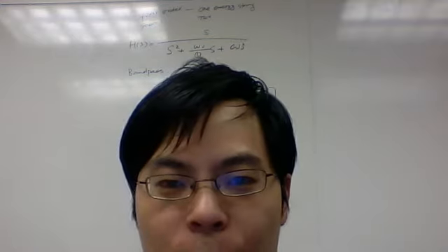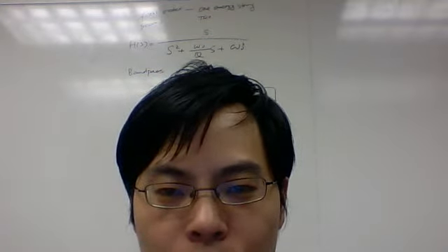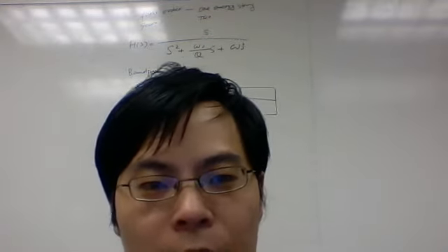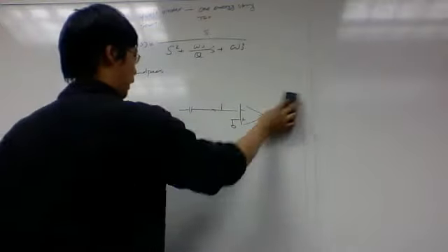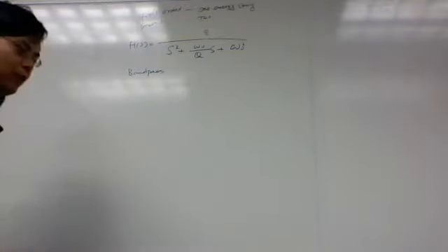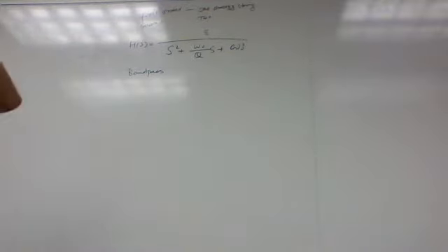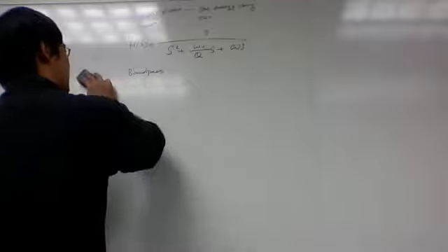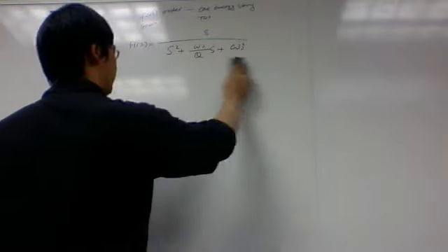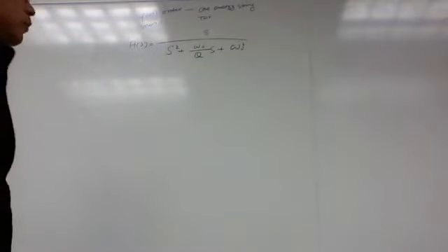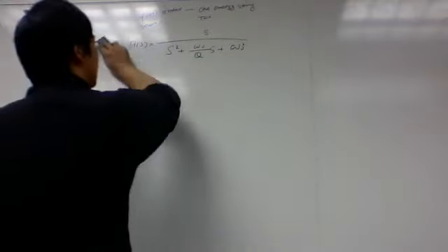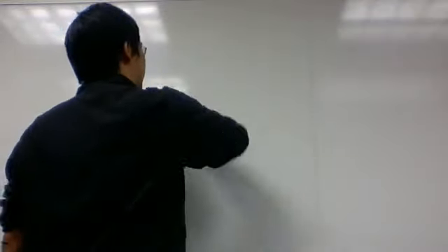We know it's called Sallen-Key. Later, if people talk to you about Sallen-Key, you at least know it's some sort of single op-amp structure, and it has the advantage of being simple. You only need to buy one op-amp and build it using some cheap RCs. But the drawback is it is sensitive to the component spread, right? If your RC values change, your pole and quality factor change a lot.